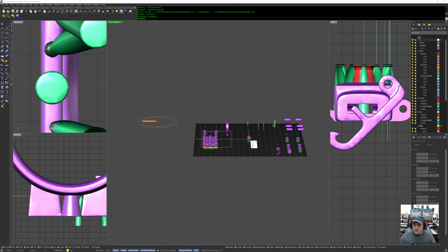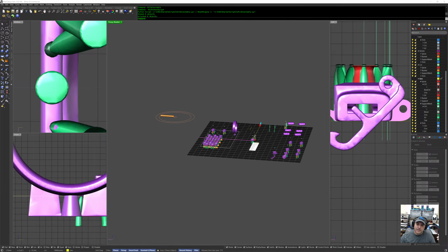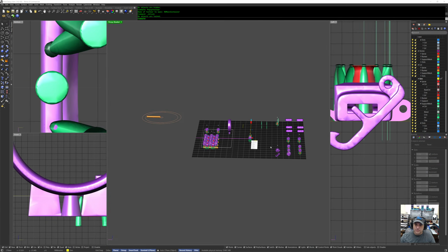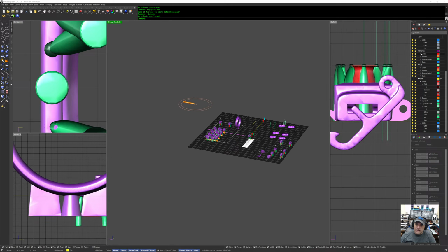But what it does is it turns all the layers on. So none of the layers are locked. It goes through all the layers and makes them unlocked and shown, and then does a show and an unlock on everything. And there is no command in Rhino that says make everything selectable. But I just did that.